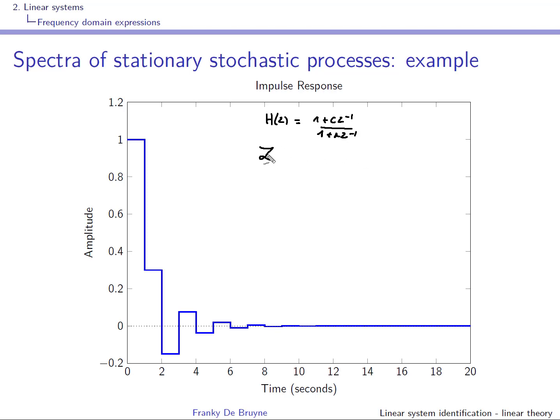The inverse z transform of 1/(1 + a z^-1) is (-a)^k times the step function, the Heaviside function. I cannot use u here because it's the input, so I'll write it as Heaviside(k).